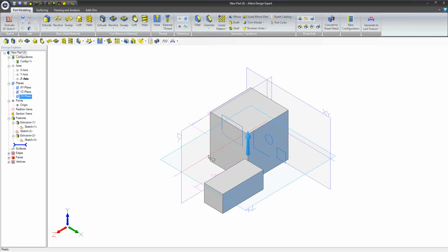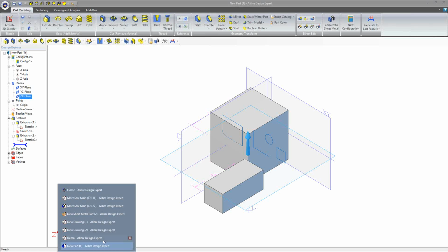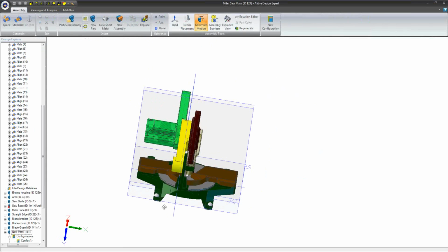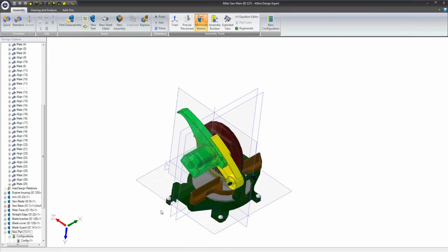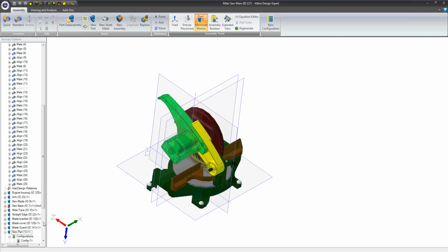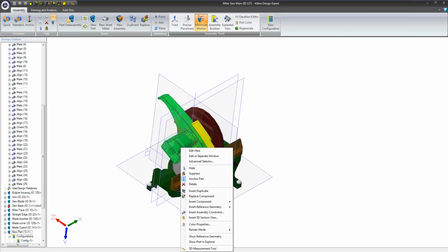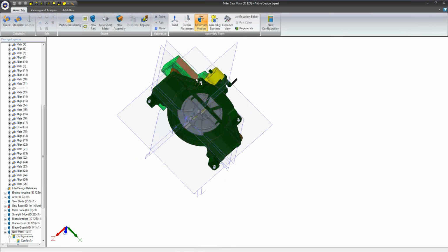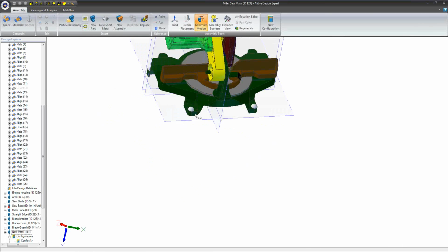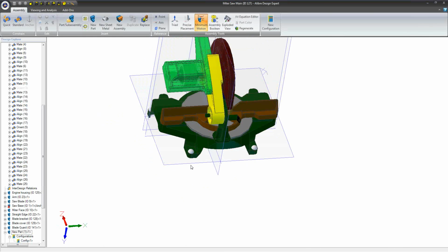that automatically depending on how you edit the different components. So as you noticed, we were doing that a little bit when we were playing with the circular saw. In this instance, all I was doing was right-clicking on the particular part that I wanted to modify and going to Edit. If I do it in this manner, then the regeneration is automatic. So as you noticed before, when I applied these holes to this part, all I had to do was close that workspace and return to the assembly, and those modifications were shown in the design.